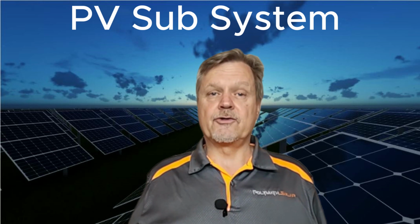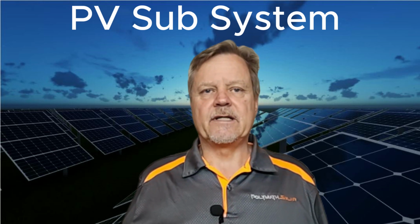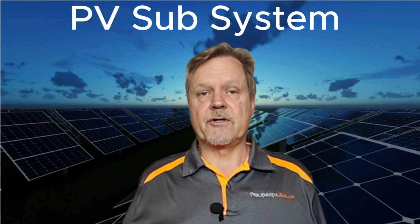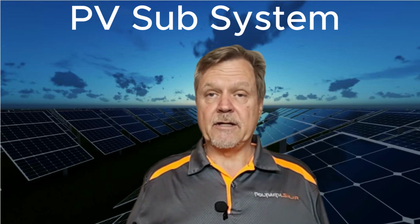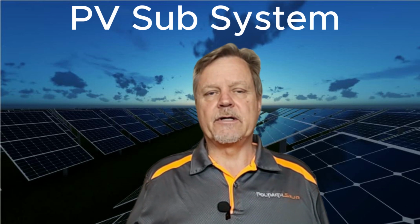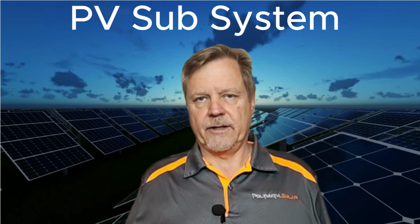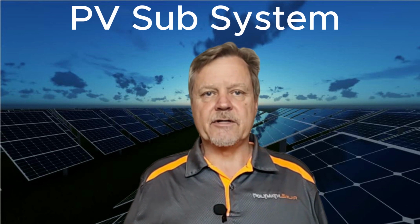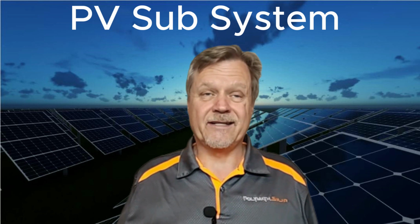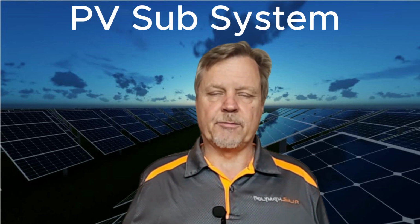If I've got too few solar panels, well, we call it energy starvation. There's not enough energy coming from the sun to keep the house going and charge the battery. So typically these systems can be programmed, depending on what you're installing, so that the priority is either to charge the battery or to keep the house going. Mostly I would suggest keep the house going, because that's real savings. Every watt that you harvest from the sun and use directly is a watt that you don't have to buy from your supplier.